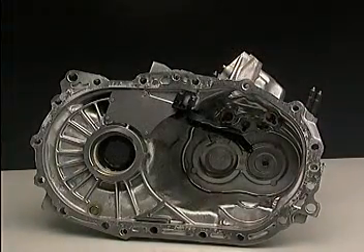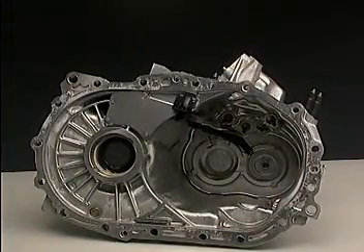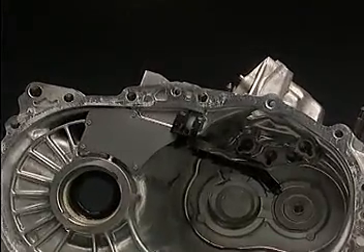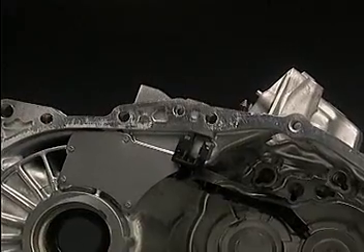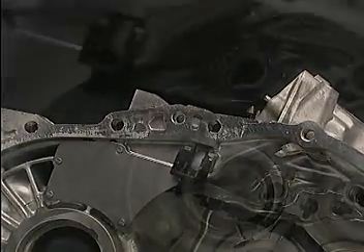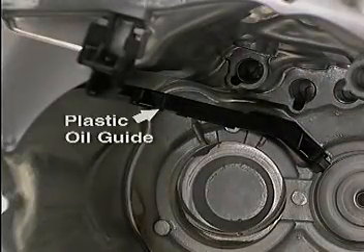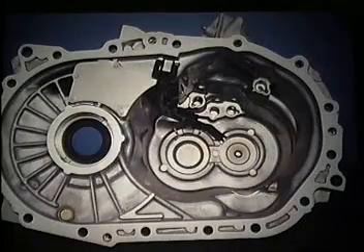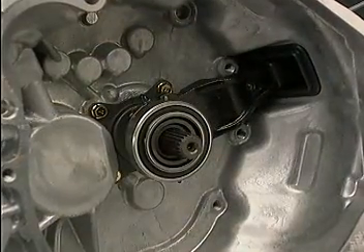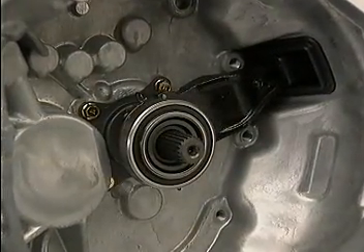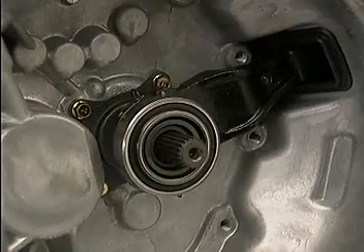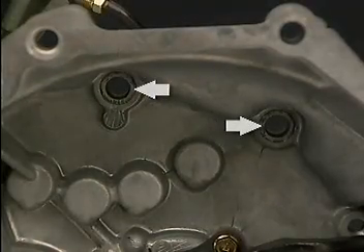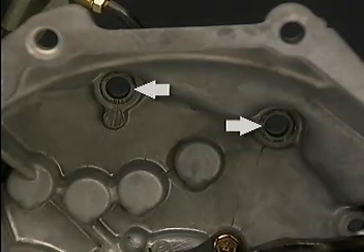To further reduce weight, both transaxles have die-cast aluminum cases. All transaxle sealing surfaces use formed-in-place RTV instead of gaskets. The transaxle case uses a plastic oil guide. A special bearing guide tap is used, and the case has a cutout for the tab. The clutch release bearing retainer design has been changed so that it can be replaced without disassembling the transaxle. During disassembly, be aware of 2 bolt locations inside the clutch housing.